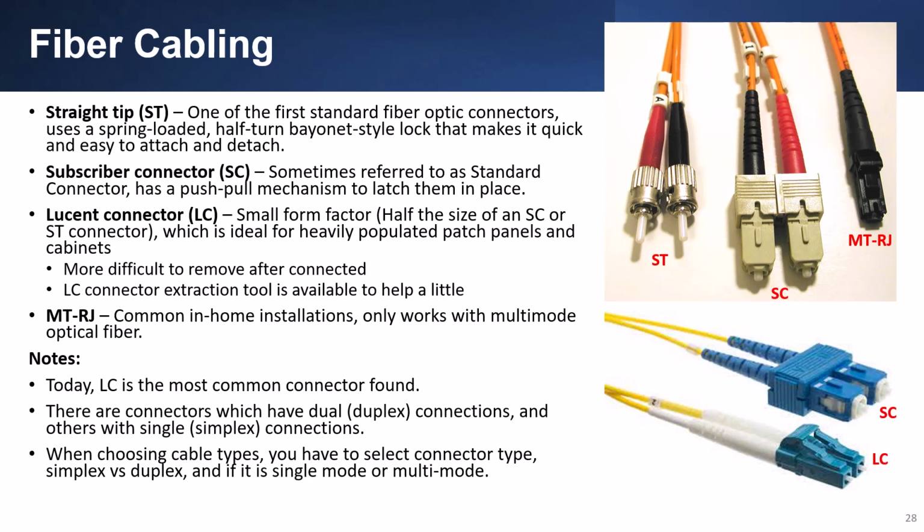The MTRJ is common in home installation and only works with multimode optical fiber. Should note, today, LC is the most common connector found. There are connectors which have dual or duplex connections and others with single or simplex connections. When choosing cable types, you have to select connector type, simplex versus duplex, and if it's single mode or multimode.